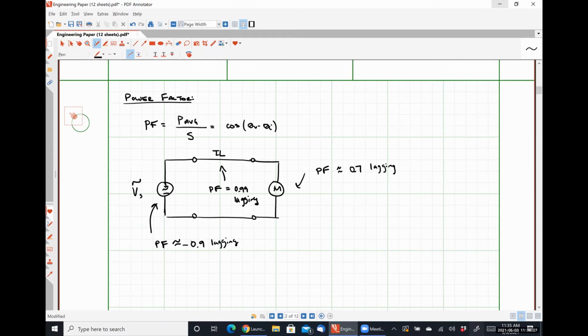Did you guys talk about why power factor matters other than the efficiency or anything like that? Okay, so let's talk about making the power company happy. The power factor, as I said, is a measure of the efficiency between the average power and the apparent power. The average power is what you as a consumer pay for, and the apparent power is what the power company pays to create. If they have to supply a large amount of apparent power, they have to purchase and burn more coal or put more wear on their hydroelectric turbines in order to generate that power. They don't like having to spend more money and not getting to charge you any more for the part that you use, right?